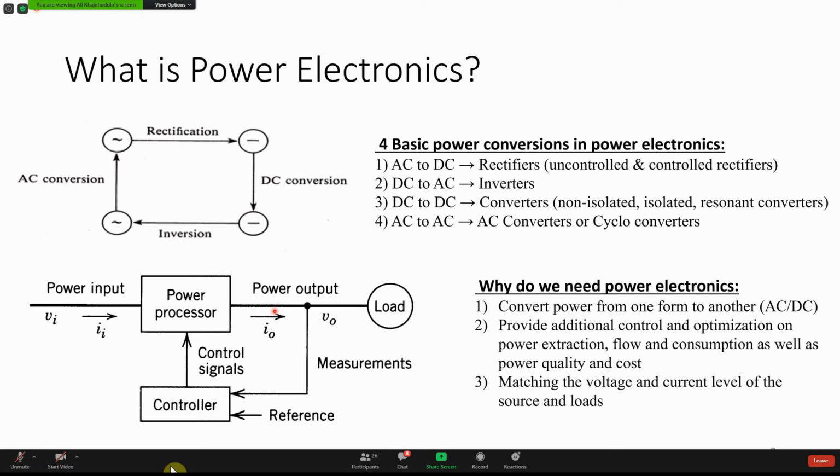If you really want to stay at 5 volts at the output, no matter how much current your load is drawing, then you definitely need a controller. The reason is that as soon as you start drawing current, all the parasitic components in your power converter come into the picture and will drop your output voltage. So the higher the current, the lower the output voltage.